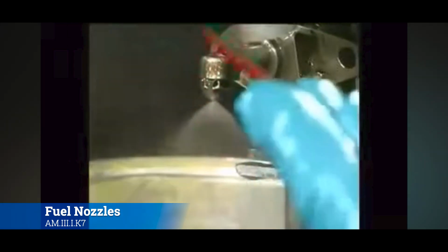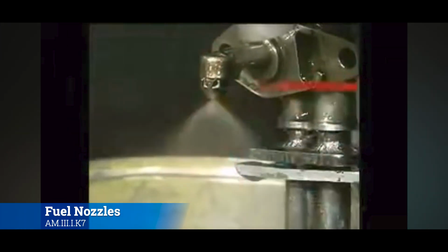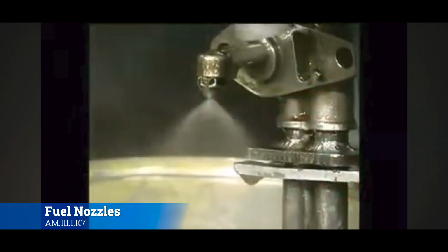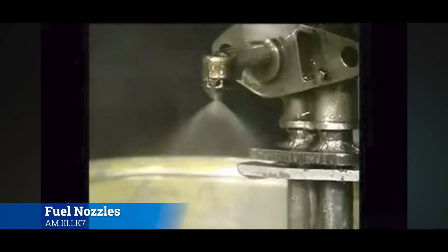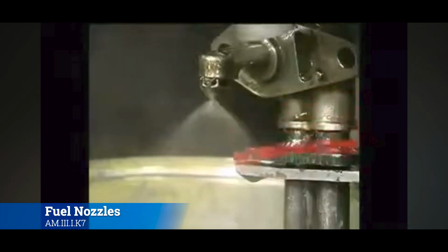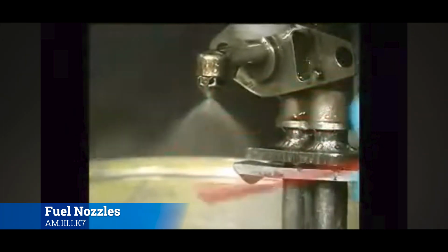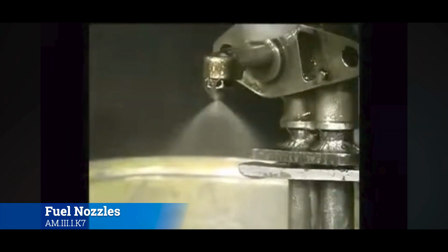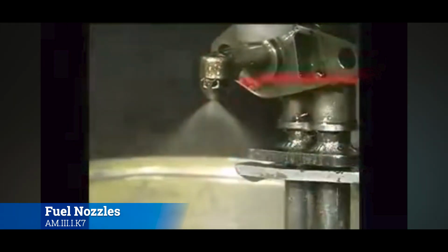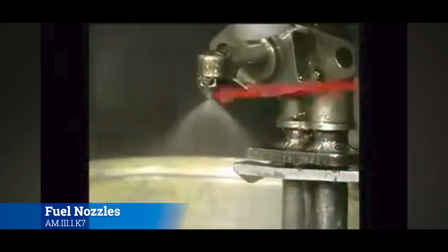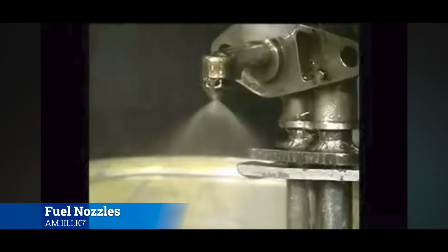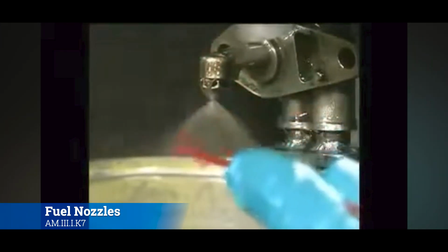You notice the spray pattern. What you're looking for in this are any dark spots, streaks, or any clouding, indicating that there's more fuel there than we should be. The main thing that this check is looking for is that you want to make sure the fuel burns efficiently, not only just for power, but also to make sure that you don't have any unburnt fuel that's going to pile up in the combustion chamber and then all of a sudden ignite during start or somewhere during the process, or that the fuel's not going to cool the combustion chamber as it's supposed to, and you start getting hot spots and you start having problems that way.